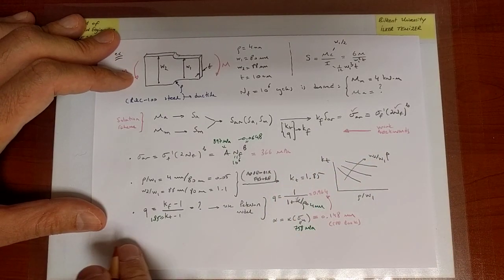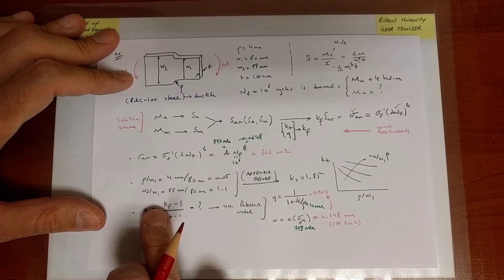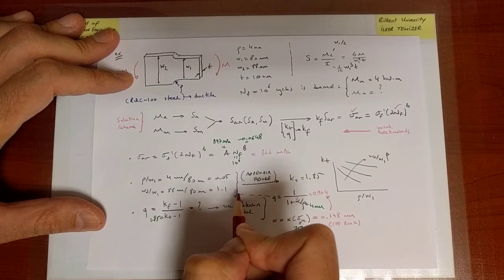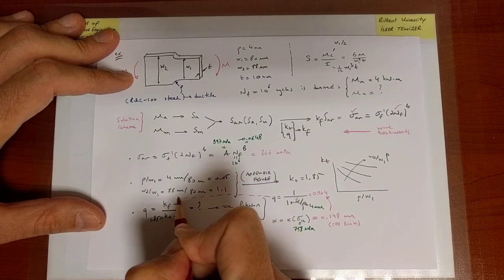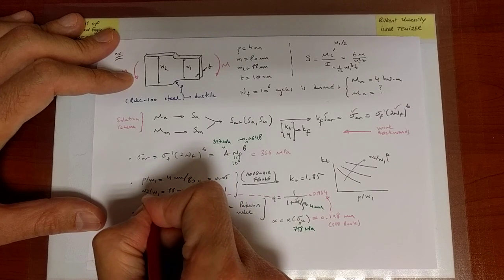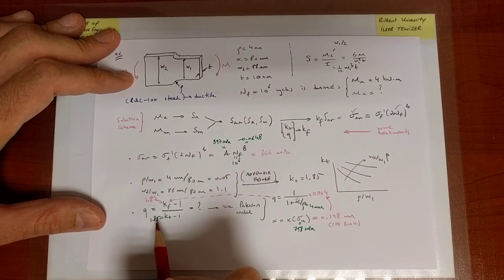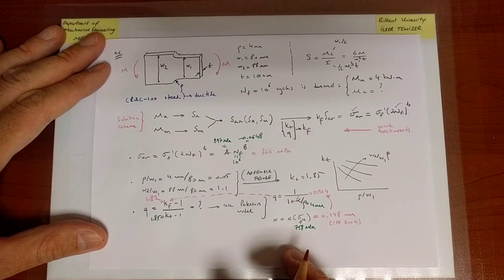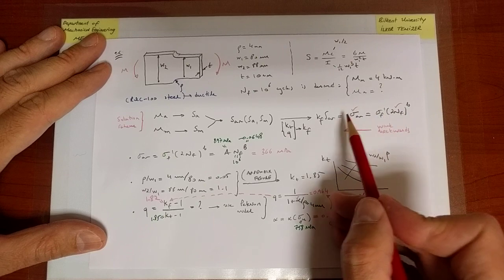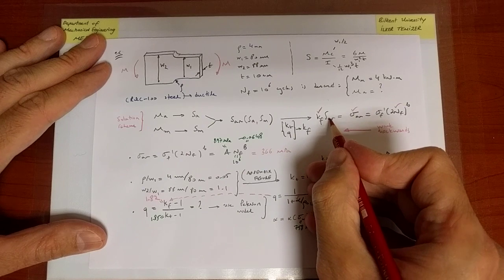So now that we know the value of Q and KT, we can go up here and determine the value of KF, which is determined to be 1.82. Remember what we had done. Given the life, we determined sigma AR, and now I've determined also KF. So now I can go and find the value of SAR.